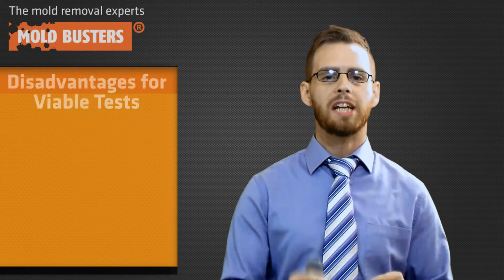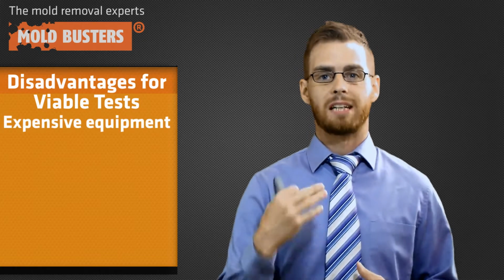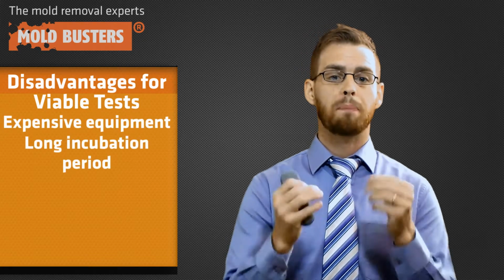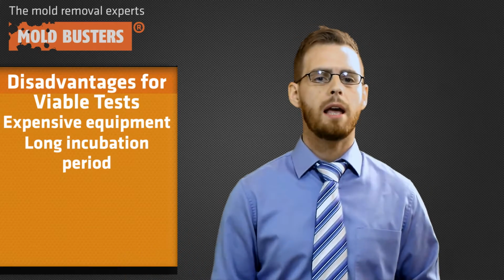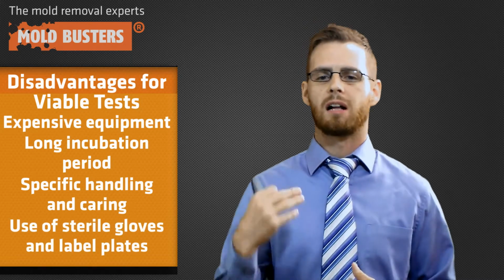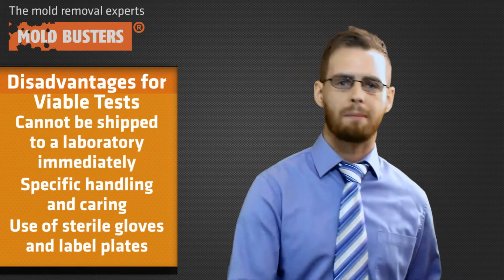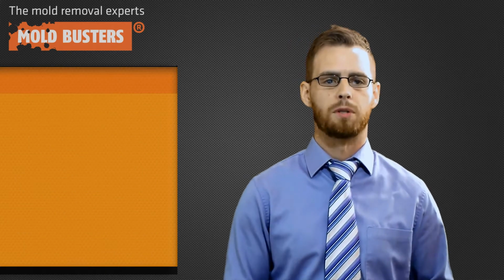Now, there are limitations with viable indoor air tests. For example, they're relatively expensive equipment. The incubation period is 7 to 14 days, which for most people is too long. It requires specific handling and carrying, and we must wear sterile gloves, label plates, mail to the lab immediately, and so forth. These processes can be very confusing.